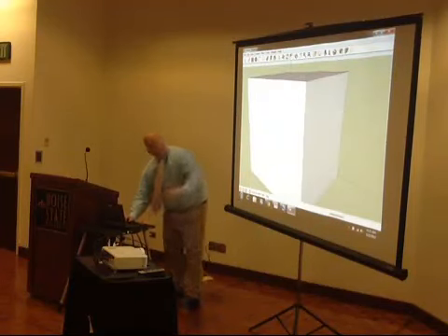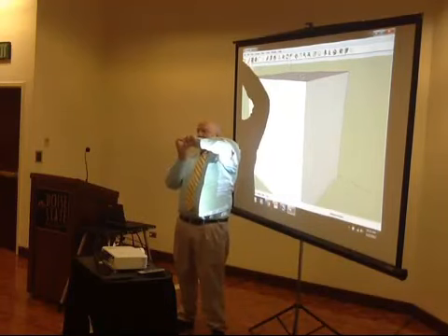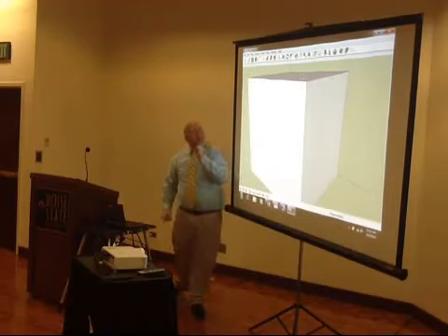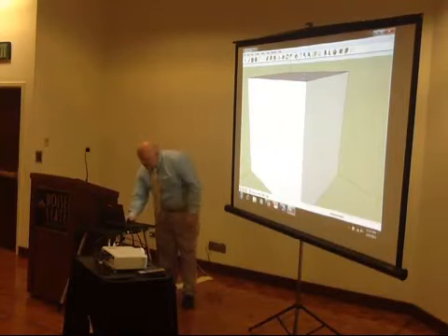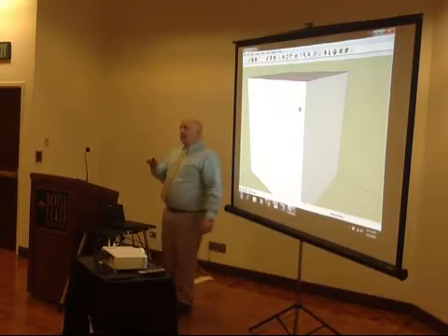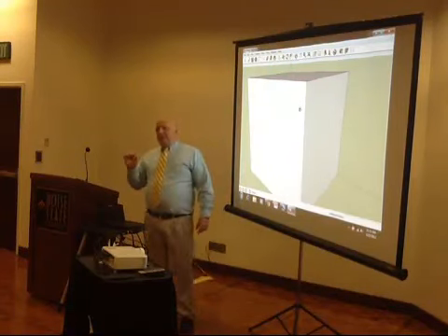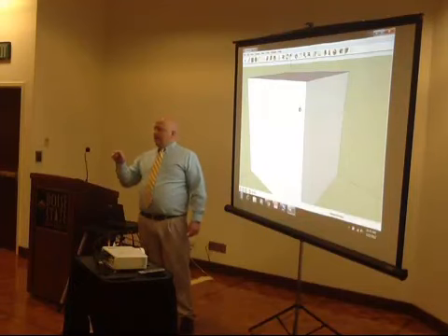I'm sorry, where's the orbit? The blue with 2 arrows looks kind of like a little globe. So we click on that and drag around. That tool will actually become your best friend. So if you have a scroll wheel on your mouse, then you can roll the scroll wheel in and out to zoom in and out on your drawing.